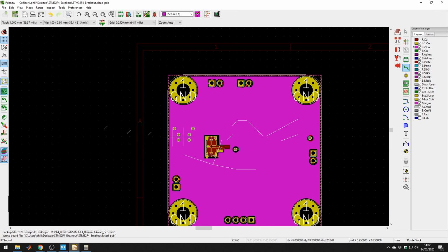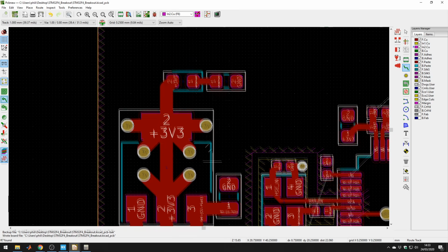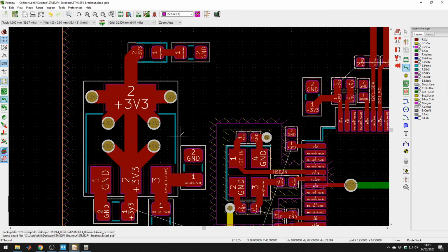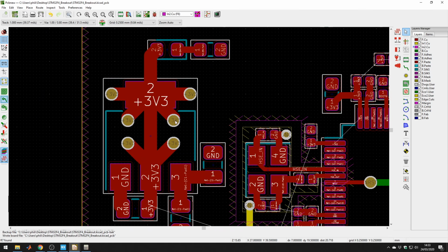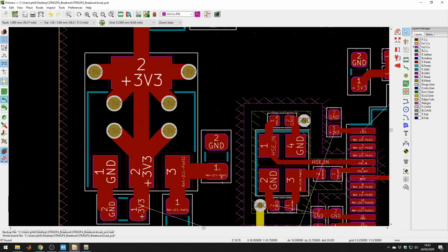So you can see they're connected here. So you want as many of these as possible to minimize the inductance, because any via will add inductance, and if you have inductors in parallel, the inductance will decrease. So you want as many of these as possible. I've had fairly large vias here, so I'm fairly content with leaving it with just these 6.